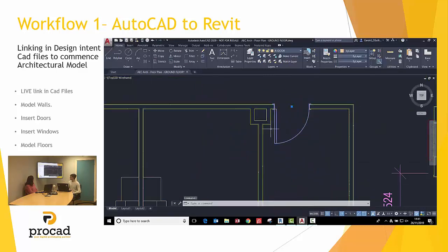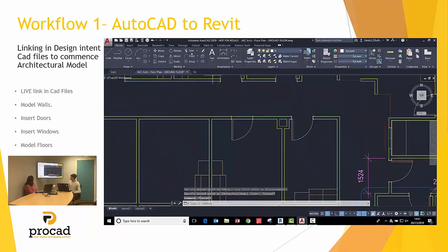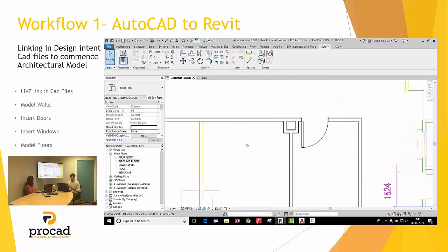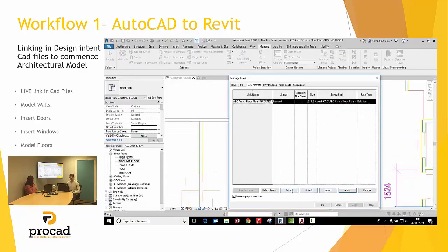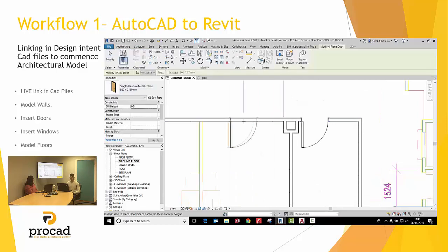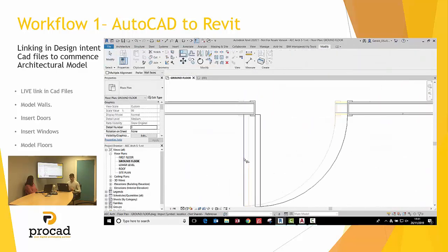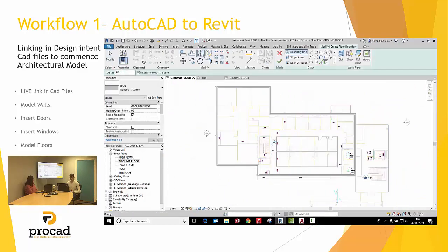From here you can see I'm going to add a new door into the CAD format, and this is how the live link works. I'm just going to trim that, and you can see that I'm going to go back into Revit, Manage Links, and reload that link, and you can see that that door has now been inserted into our Revit model. Again, simply placing the door into the wall, it automatically creates the opening and the door itself.